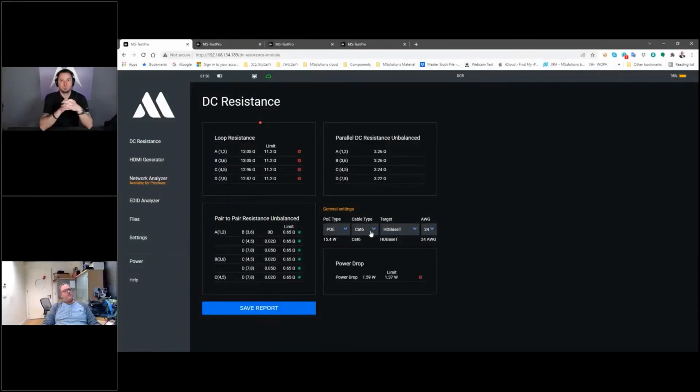So it is okay that you are improving the cables, but you need to understand with different types of cable, different category cables, even though it's a Cat6, you can have different gauge implementation, and all of this will affect the different limits that you have. So on the limit for loop resistance, you are failing, but on the limit for unbalance between pair to pair, it will work. What will be the results for this?